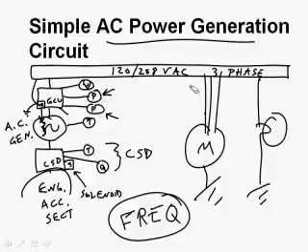So now, if we stop worrying about frequency for just a minute, then maybe we can realize that, wow, we've got to take power off of the engine. We've got to control the output. In this case, not only control the amps to maintain voltage, but we've got to control the RPMs to maintain frequency. But hey, we can turn stuff on, turn stuff off. You'll notice there's no battery.